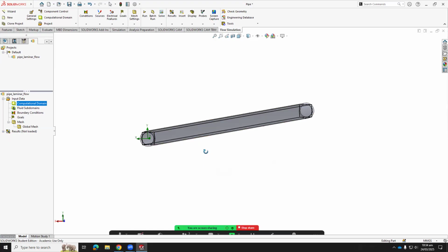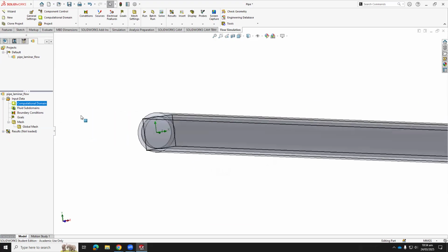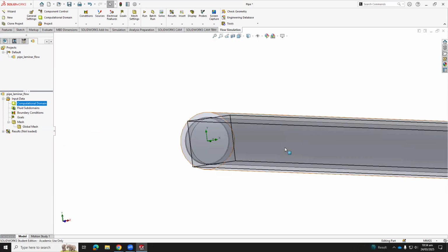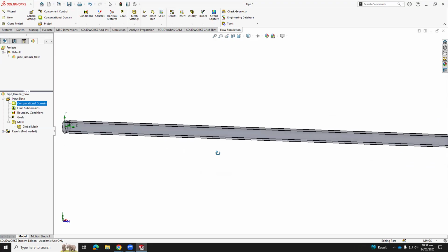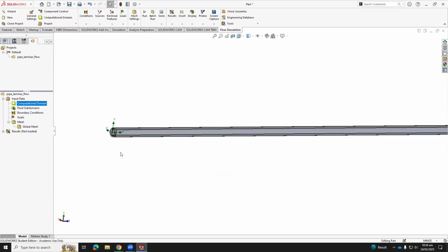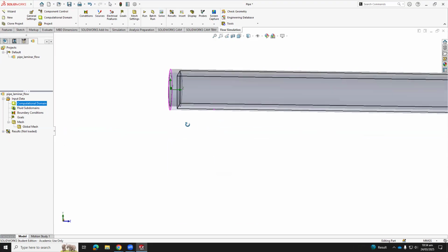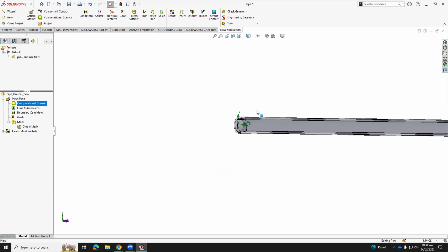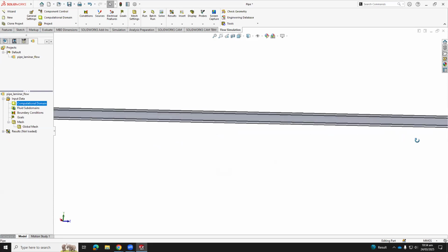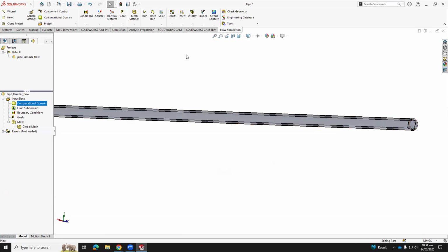Okay, so let's select boundary conditions. What I would do always, I explained these boundary conditions. So this is where the fluid is going. I have a velocity from that face and velocity and pressure opening on that face. But I don't like that face. I'll go back. I want to go back to my geometry. See where I'm going? The arrow.